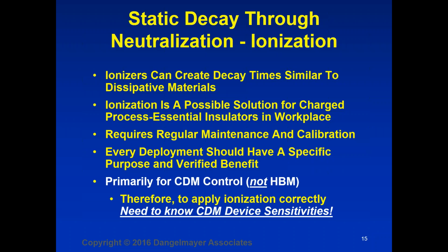To apply ionization correctly, you need to know your device CDM sensitivity. How sensitive is your device? Because that's going to determine the ionizer that you choose for your application. And I know that most of you are going to say we have a great deal of difficulty finding the CDM device sensitivity. Fortunately, in most applications in the electronics industry, outside of the MR head industry, the ionizers that are easily available have balanced voltages that are much lower than the device sensitivity, so we generally don't have a problem. But if you really are concerned that you have a very sensitive device, it's really important to find out what the actual sensitivity of that device is.